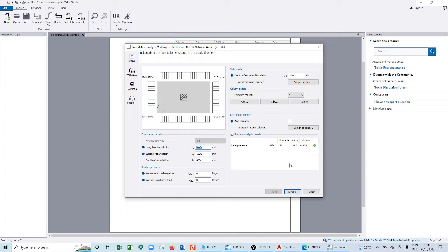Sometimes when the friction is very low, then the soil easily goes over, the foundation can easily slide. Now, it depends on the nature of the soil you have. If you have clay, you know that clay already gets water and becomes so plastic. There are products that give you the angle of friction, they give you from the lab, everything. So you have to have those values with you. You will just feed in there.